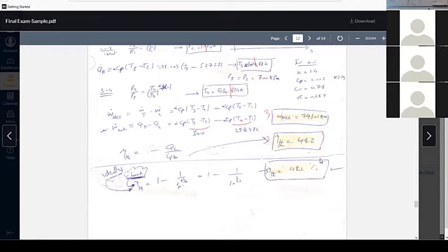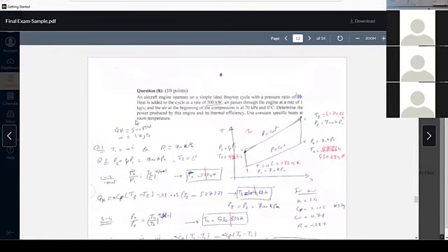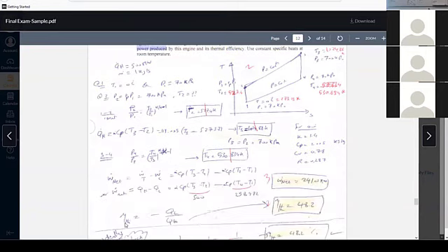Okay, guys? In the exam, if I did not ask for anything except thermal efficiency, you would not need to go through the steps. Some guy was so smart. I like his solution. He said, you want thermal efficiency and work and power? That's easy. He said, I have thermal efficiency from rp, correct? He can get the thermal efficiency easily. He said, I have the heat and the thermal efficiency, so I can get the power produced. The thermal efficiency is W net over Q high. And he solved it in 1 minute.